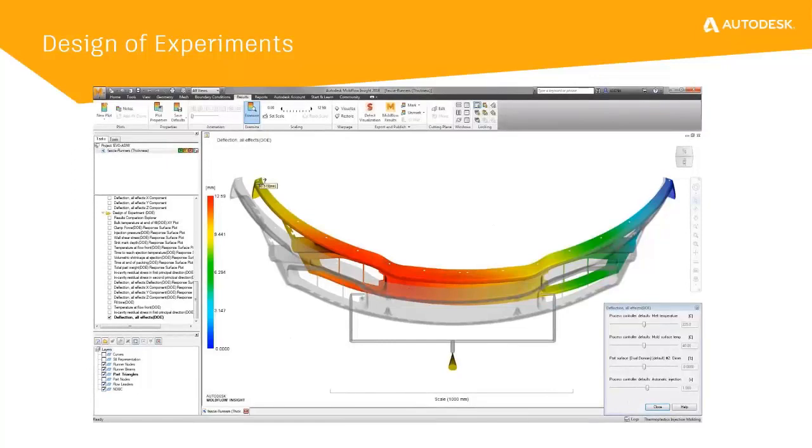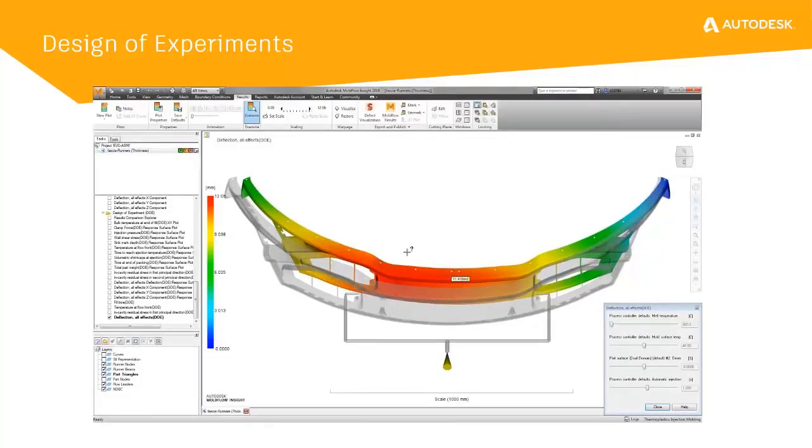There are also other ways to evaluate specific DOE results. For example, this animation plot provides all of the input variables on a sliding scale to allow the user to adjust variables and immediately evaluate the response. Here we can easily see what happens to the deflection of the part when melt temperatures increase or decrease, and the same for mold temperature.